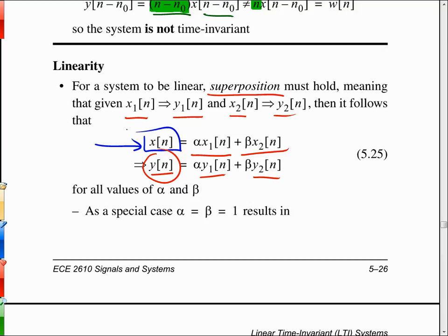But if you were to just back the gain levels down on both of the inputs you're mixing in, you could maintain an undistorted output. You just can't keep raising the power level indefinitely, and that's true of any electronic circuit. You can only provide so much total power output.